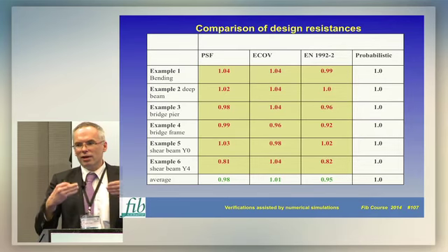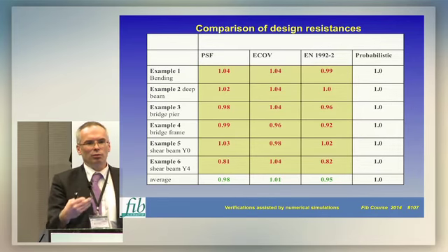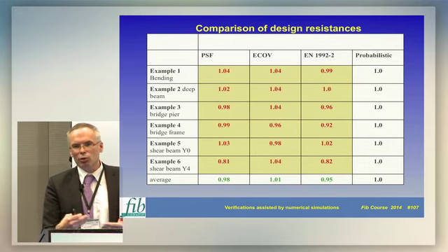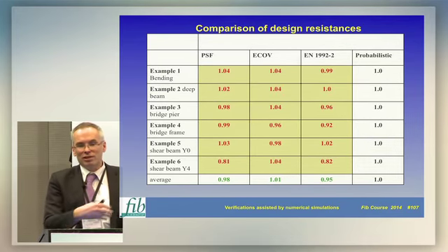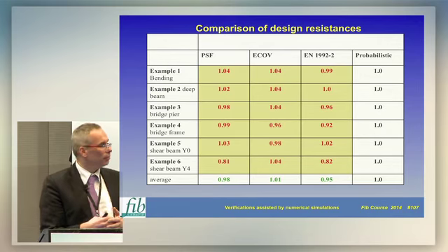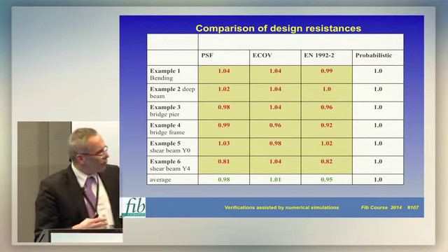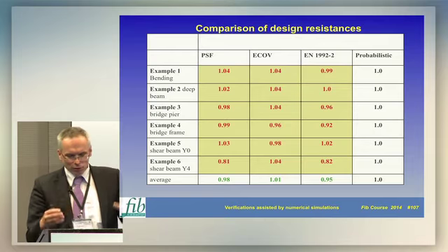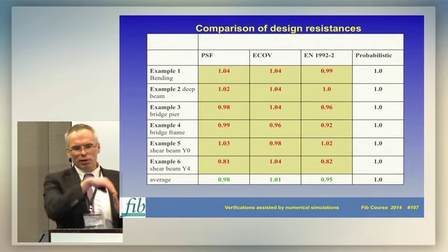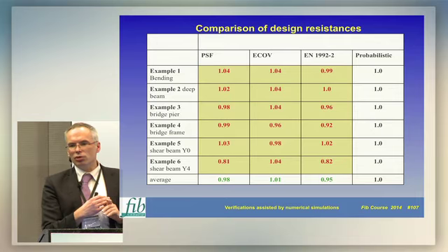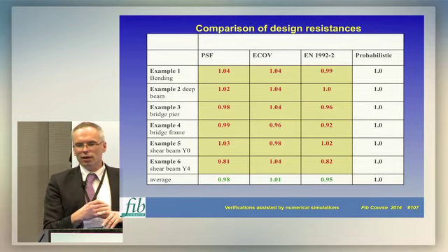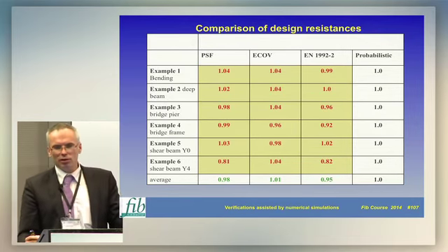So try to be as close as possible as would be the standard approach taken or assumed in the code. But then I think for resistance, it's also important that with our method we have to make an assumption about the distribution of resistance, and there we used log normal distribution.